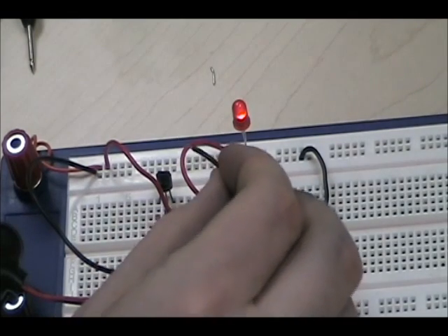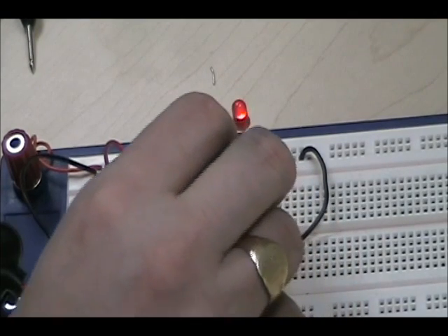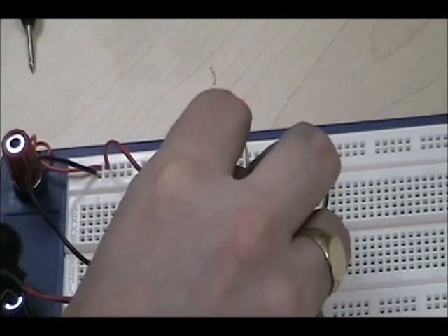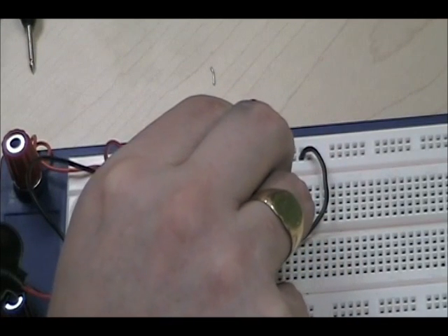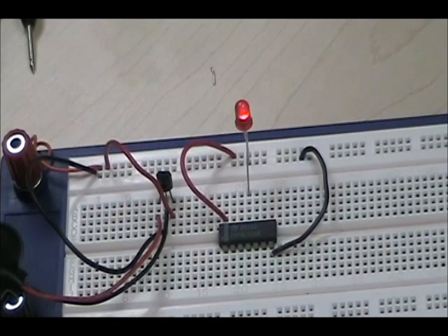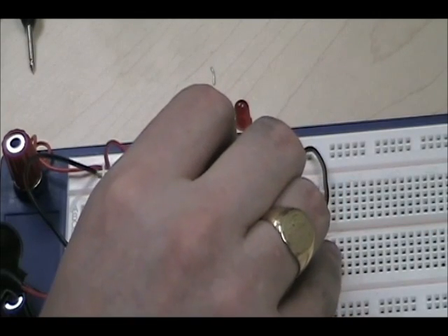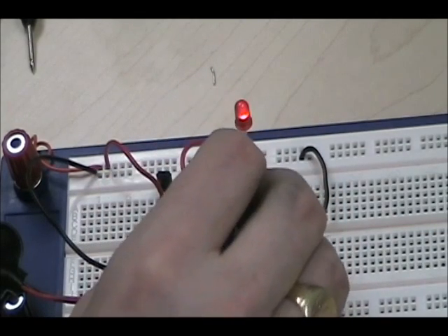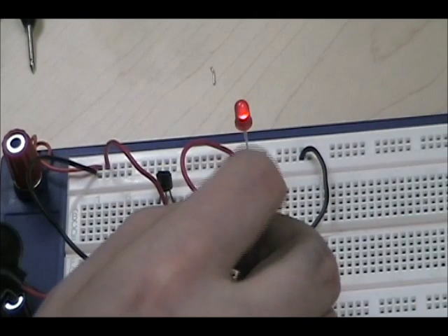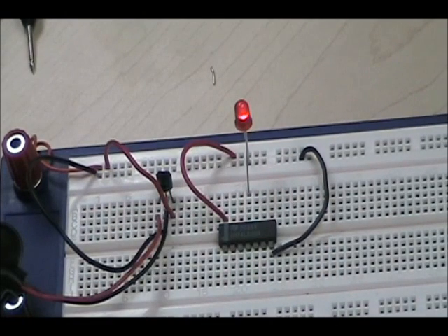So if I ground either one of these, then the output goes off. You don't want to leave these floating. That's what's considered floating. So that's the AND gate. If we ground any of the inputs, the output is off. Commonly, we'd have signals coming in, high or low signals, to determine the output. But for now, let's move on to another chip, shall we?